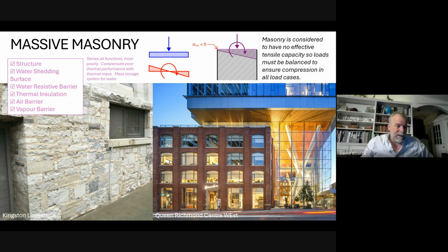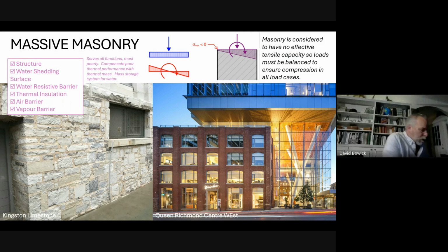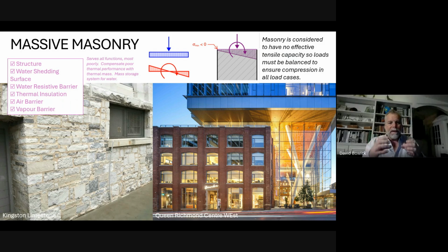Now, here's the thing about masonry. I'm going to grab some books to give you a little example. Similarly scaled books off my shelf. So we consider masonry to have 0 tensile strength. Of course, it has some. If you have 2 bricks and you bond them together with mortar, you can't pull them apart by hand. There's a tensile bond there.